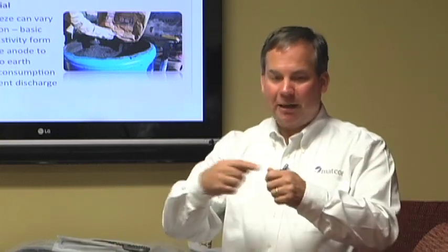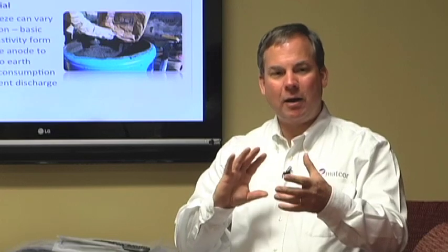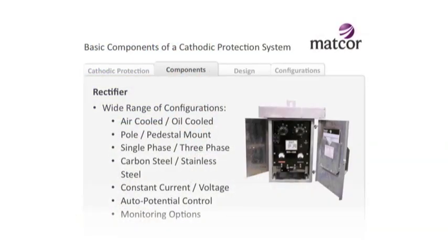And what that does is it's like when you have a light bulb in your house. The light bulb is actually that filament element in an incandescent light bulb, but then there's a housing around it so that the light discharges really off that housing. Well, that's how the coke backfill works. The coke allows current to discharge evenly off the entire anode so that the anode wears evenly, and then it discharges from the coke into the soil.